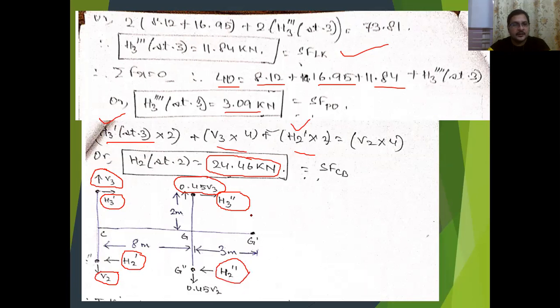The main concept is that there are two important things: the shear force values will be the same, just the direction of the shear force of the columns, which was from right to left, while considering the second floor will be from left to right.